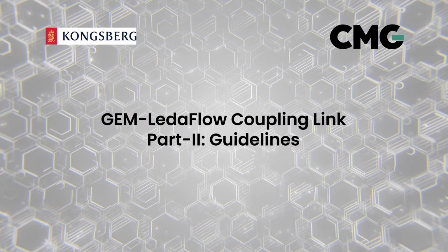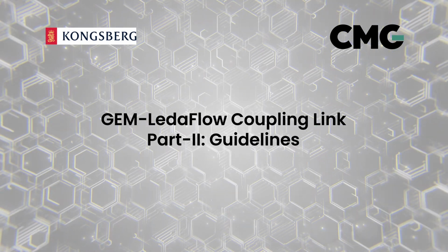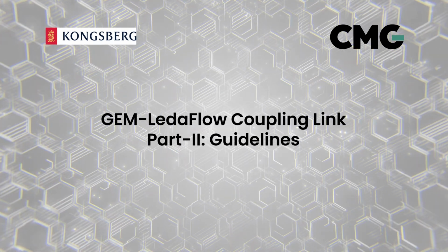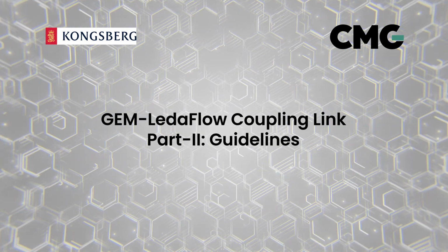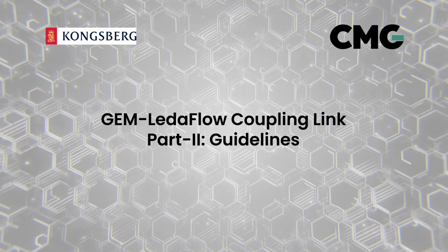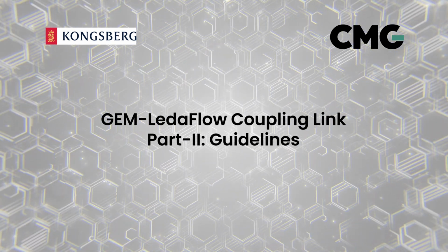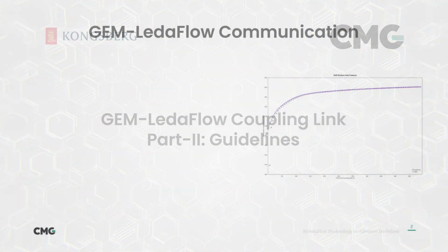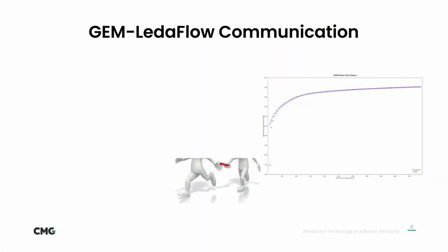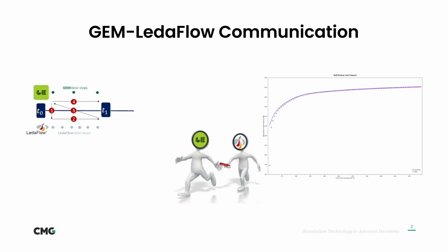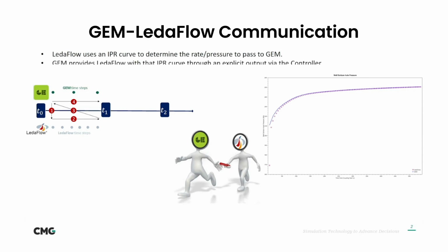My name is Reza Malakuti, and in this video I would like to give you some guidelines about how we can successfully couple GEM and LedaFlow via our coupling link tool. In the coupling process between GEM and LedaFlow, one of the key criteria that can help us understand if the coupling process has been successful is the reasonable match between the estimated bottom hole pressure by each application.